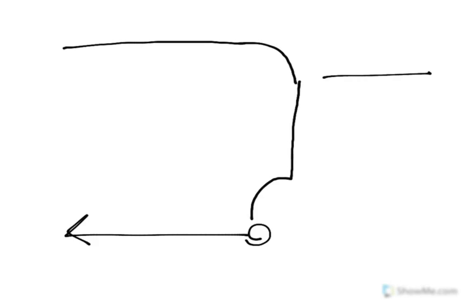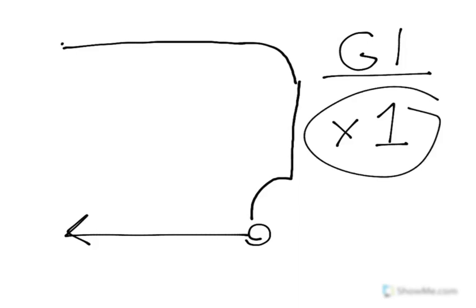First thing we need to do is go back into linear mode, a G1, and then specify the distance that we're going to be moving to, or the location, which is going to be simply an x1, right below the y coordinate. Or I should say, the y coordinate is not going to change for this motion here. So we're only dictating the x coordinate of motion.